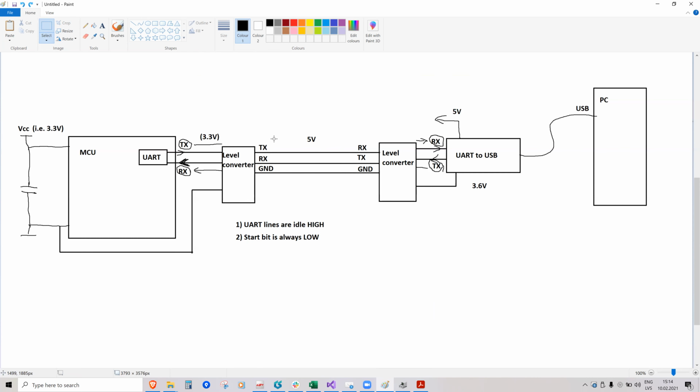So the transmitter, I will draw a red circle around it. Transmitter is the output. It controls the line level and it sets this TX to RX line high all the time. So when I connect the second device, it senses on the RX line that the line goes high, so it knows that something is connected to the other end and you can communicate, and vice versa.